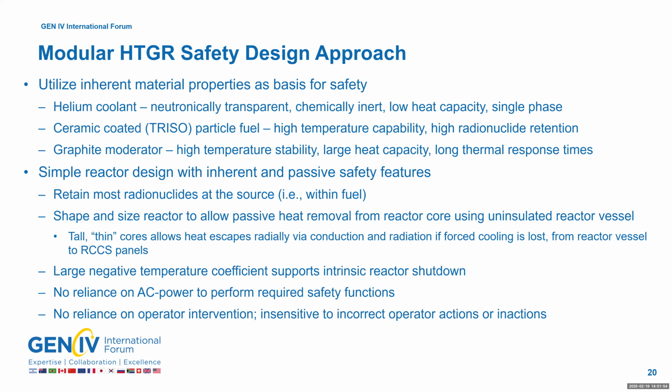So in terms of inherent and passive safety features, again, the argument fundamentally within the safety case is that most of the radionuclides are retained at the source, meaning within the fuel or the fuel compact. The shape and size of our reactor designs are by design tall and thin cores. The idea here is that you attain passive heat removal from the core using just conduction and radiation heat transfer, so fully passive, in the case of a loss of forced cooling. I'll show a picture in the next slide.